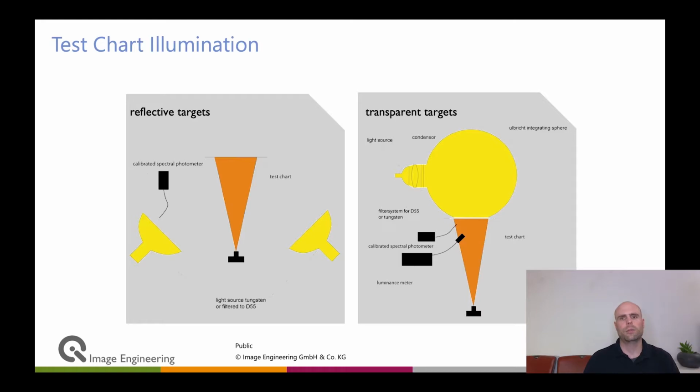For today's cameras, in most cases, if you want to measure dynamic range and cover the entire range of OECF, so how the camera reproduces luminances, you need a transmissive test target, and you need a powerful or good performance light source behind that is uniform, stable. So for example, the LE7 of Image Engineering with IQLED technology, or an LG3, so high quality light sources.